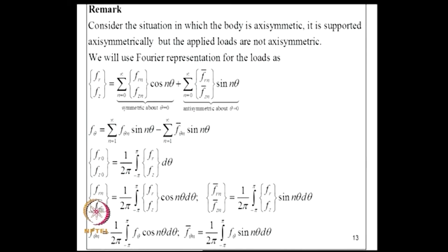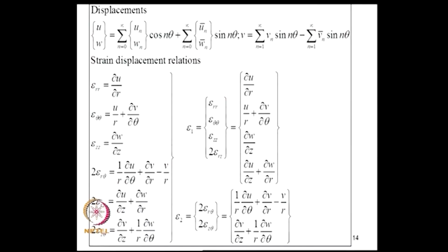Now, the idea of this formulation is we will develop one finite element model for each of these terms, and we will produce an ensemble of models, and we will synthesize the total response by summing over the responses for each of the models, each one corresponding to one component of these excitations. So, how to do that, we will just quickly see a few steps.